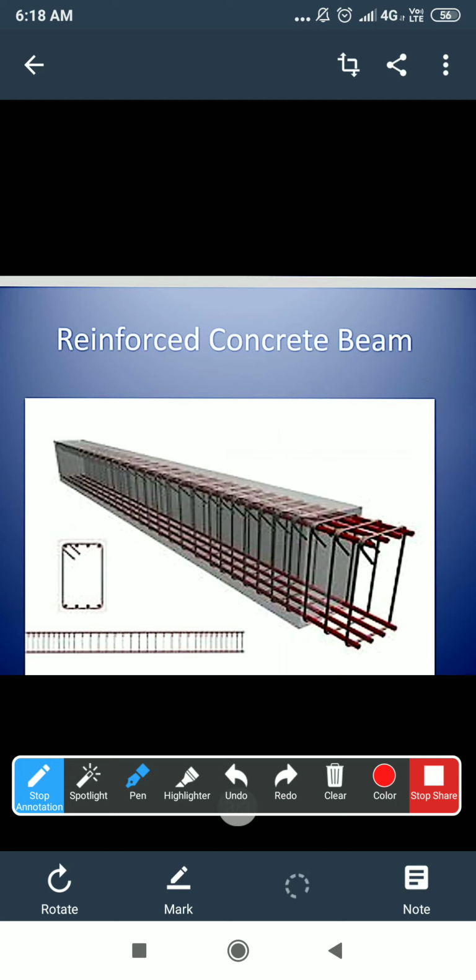Let us consider the same example of the beam bending in this direction. Without the provision of any steel member, the crack will propagate completely till its top fiber. In the initial stages there will be a formation of cracks like this, and in the absence of reinforcement, the cracks will propagate completely till the top fiber.